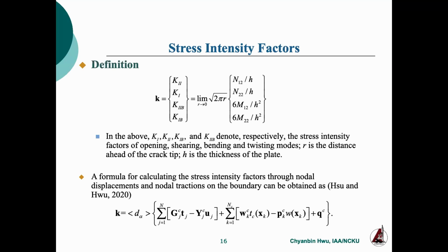This is their definition. But according to this definition, you need to have the data near the crack tip. But we say that if we use the special fundamental solution, we do not need to have the fine mesh near the crack tip, even in the entire plate inside, no mesh. So if we only have this definition, there is no special use for our developed boundary elements.